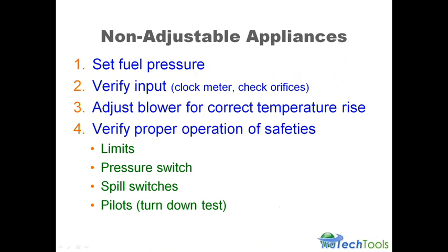You're going to get more gas, and you're going to increase the input. It's going to lower your excess air. And when you lower the excess air, especially on a condensing appliance, now you're going to stop the dilution from happening, and you're going to condense more of your water out of your gas, and you're going to get that latent heat out of the flue gases, which is what you want to do with that 90+ appliance.